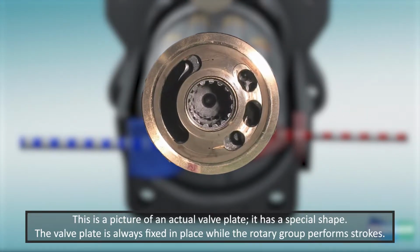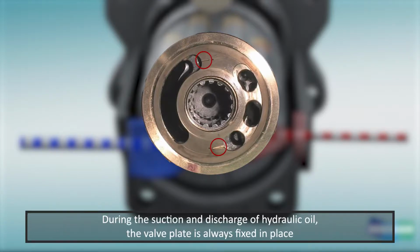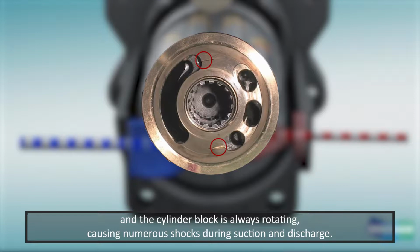This is a picture of an actual valve plate. It has a special shape. The valve plate is always fixed in place while the rotary group performs strokes. As shown in the picture, there are two grooves on the valve plate. During the suction and discharge of hydraulic oil, the valve plate is always fixed in place and the cylinder block is always rotating, causing numerous shocks during suction and discharge.